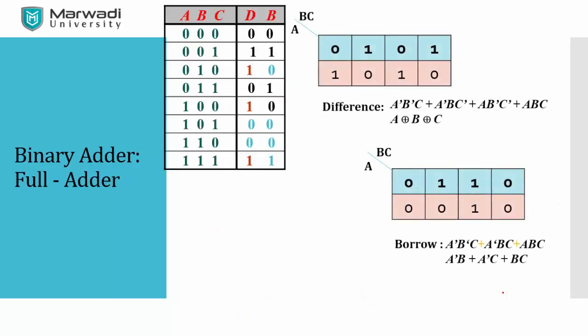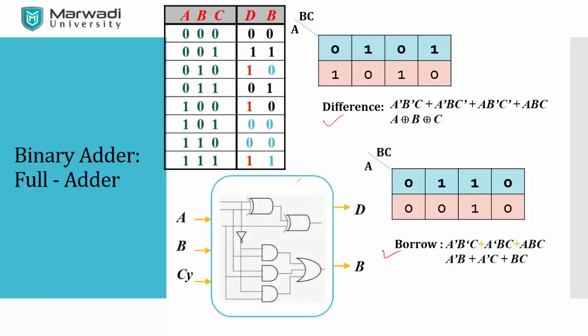So you will make the K-maps, you will get two Boolean equations for two different things, same as what we had done for the sum and carry, here the difference and the borrow, and try to implement using a combinational logic block. So we have three inputs A, B, C, and outputs Y, the difference, and borrow. Inside this we have a combinational logic.